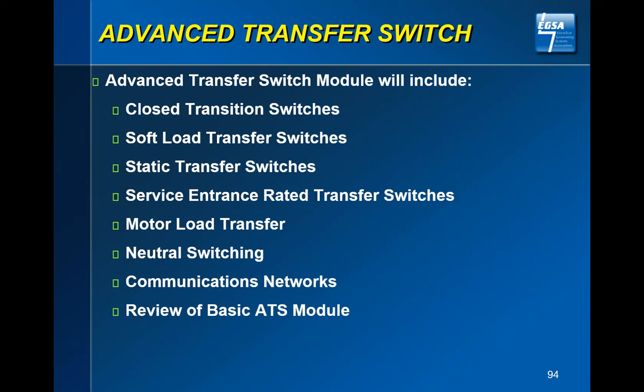Service entrance rated transfer switch will be covered. To give you the highlight of that, we will take a transfer switch, and in lieu of relying on the circuit breaker from the utility, we install that breaker. We have the breaker included with our transfer switch.